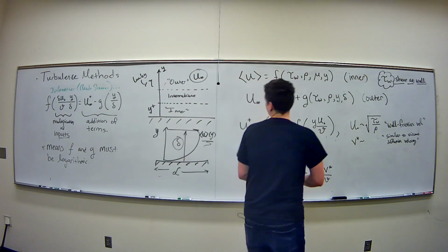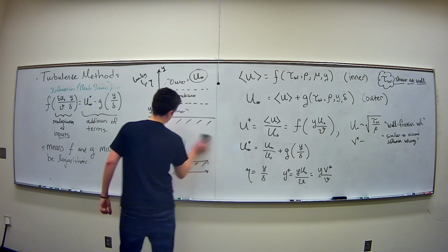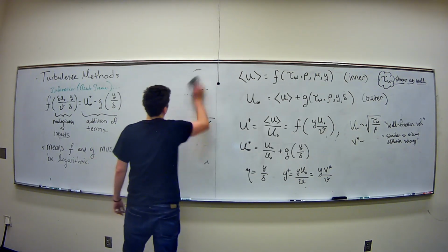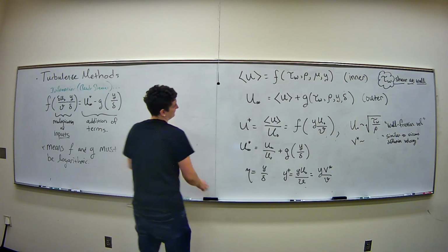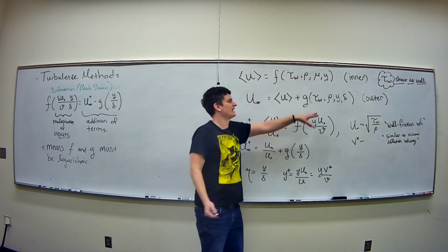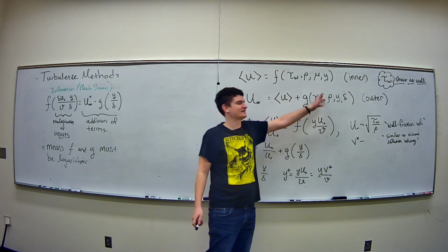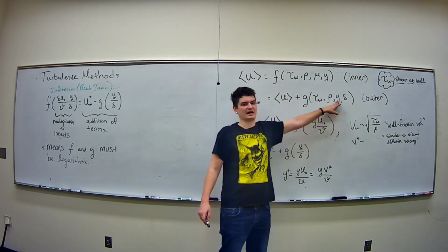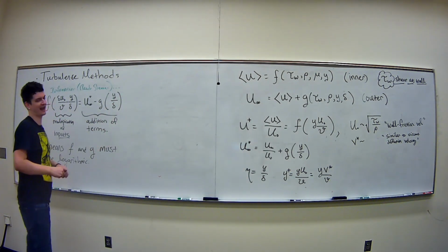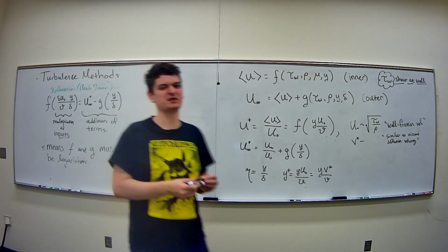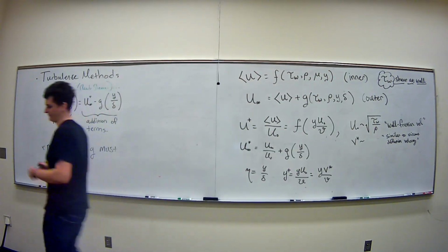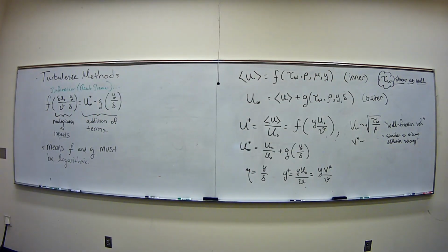So that's really why you get this logarithm. There are many ways to show it, I think, that work around just this principle. If I have an inner wall function that has to be related to viscosity, then an outer wall function that shouldn't have viscosity related at all, but then some boundary layer height, and then I have some matching condition, well, that means that it has to be logarithmic. Some people redo this with a differential equation, but they're reaffirming this physical argument, I think, because they know where to go.